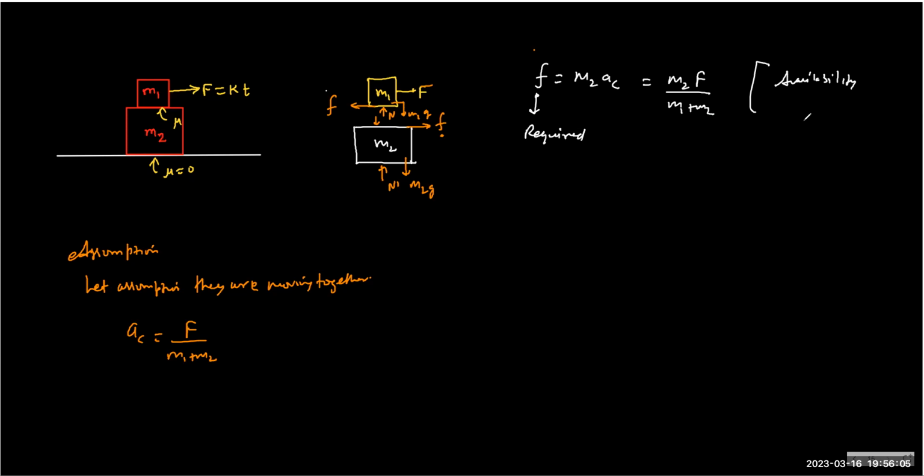What if you have 120 rupees? Yes. 110 rupees? Yes. In fact, even if you have exactly 100, the deal is done. The whole idea is: if the required friction to move together is less than or equal to the money in your pocket, which is called the limiting friction, your job is done. So the availability is called Fs max. And for Fs max, we do have a formula.